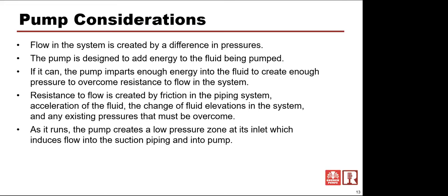Moving on a little bit here, pump considerations. When a centrifugal pump runs, it's creating flow in the system by creating a difference in pressures. The pump is designed to add energy into the fluid being pumped, and if it can, it's going to influence enough energy to be able to create flow.